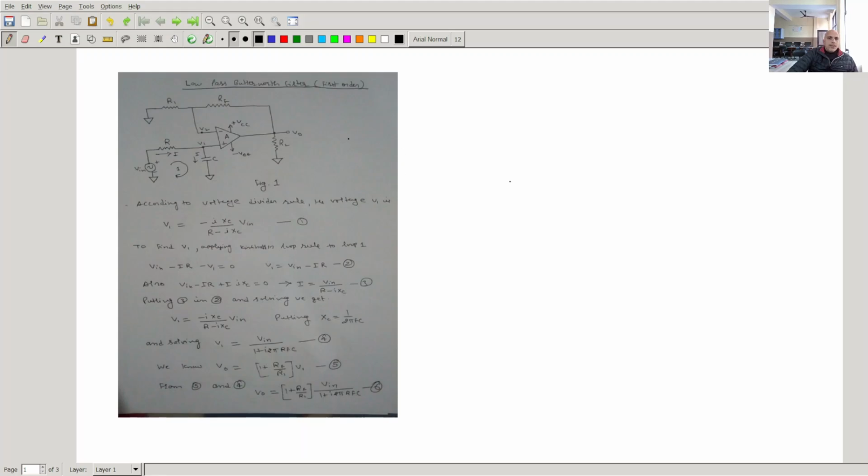In all the filters, whether it is a low pass filter, high pass filter, band pass filter, or band reject filter, we will first design the circuit of first order, second order, and higher orders, and then we will find a mathematical expression for the transfer function that will give us the relation for the gain of the filter, how the gain of the filter depends upon different components of the circuit, right? So the circuit of this first order filter is visible here.